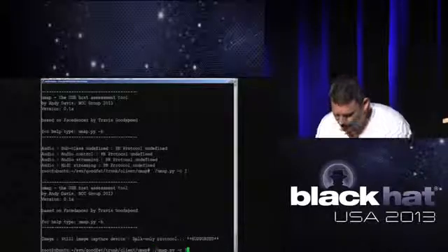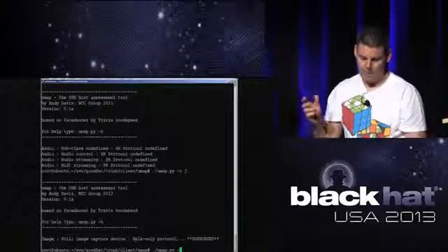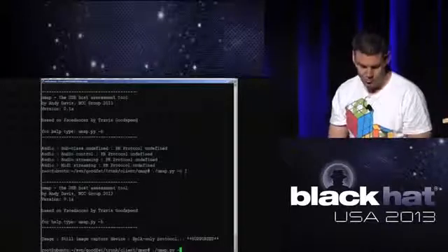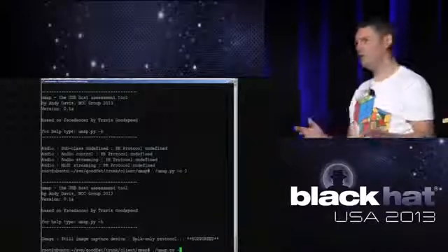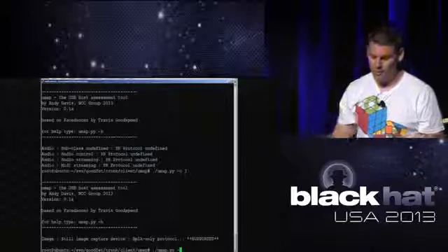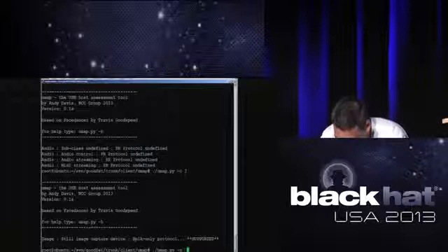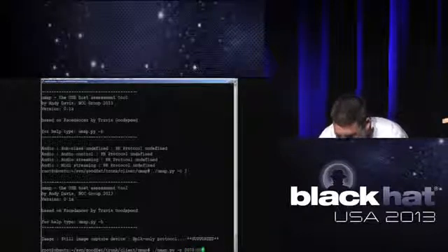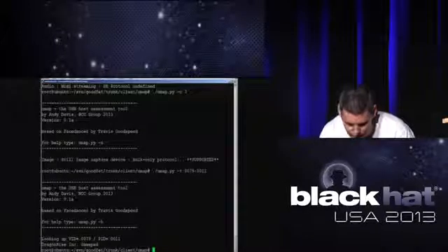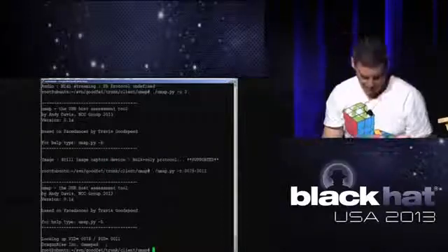Another thing you can do with UMAP is if, for example, you've seen VID and PID, the vendor ID and product ID numbers in the captured traffic, and you want to decode those. I mentioned that there's a publicly available list of all the registered VIDs and PIDs. So the tool downloads that and maintains a local copy, and you can do a lookup. So for example, that's VID and PID. And so the vendor is Dragon Rise Inc., and the product ID is for a gamepad.